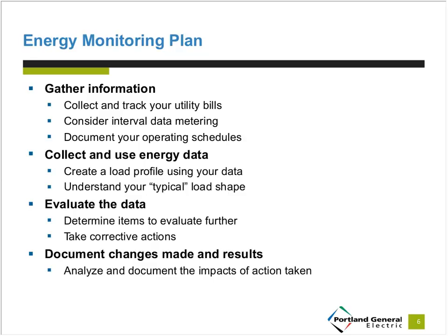You create what we call a load profile. The load profile really shows you how you are actually using energy. It could be a load profile for the year, for the month, for the week, or for the day. We'll show you an example, but you can actually see when you use the most energy within the period you're looking at.